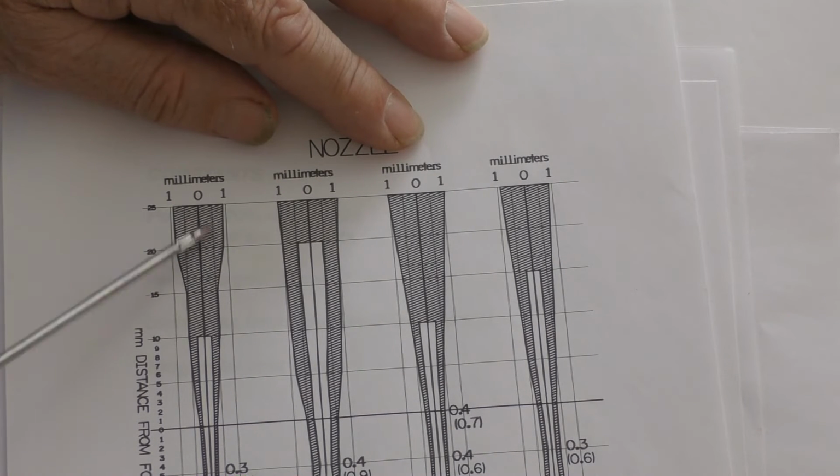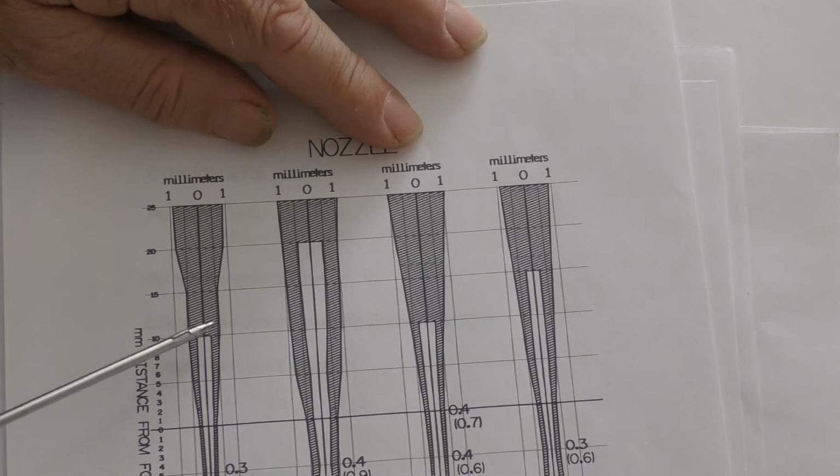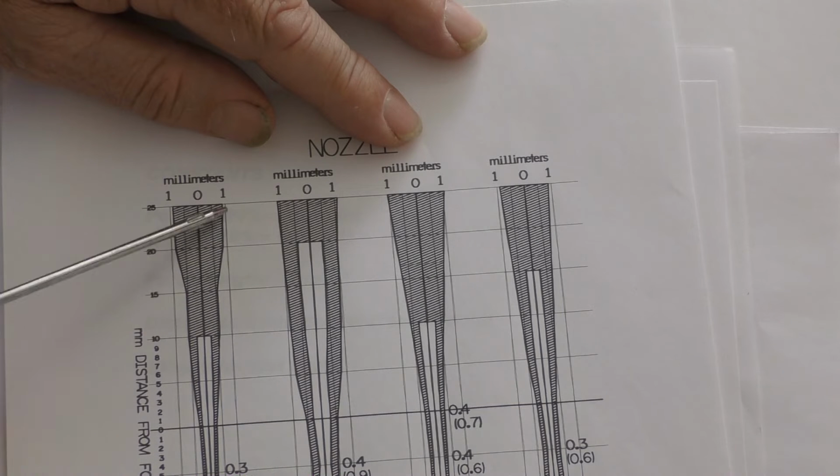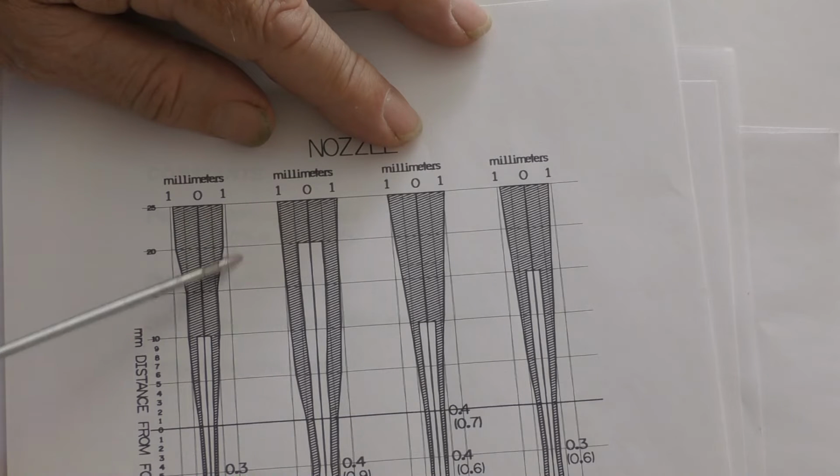Now, as I said, remember that this hatch section here is the scorch mark, the biggest scorch mark that I could find. Now, there are graded scorch marks in that close to the hole it may be dark, and yet furthest away from the hole it'll just be a light scorch. Well, that's what this is. This is the light scorch boundary, or as we get closer to the focus point, we don't get a light scorch, we only get a dark scorch. But it's the scorch boundary. Now, that isn't the same as the shape of the beam, as I just explained to you. The beam light travels more or less in straight lines. So you'll see these funny shapes on here.